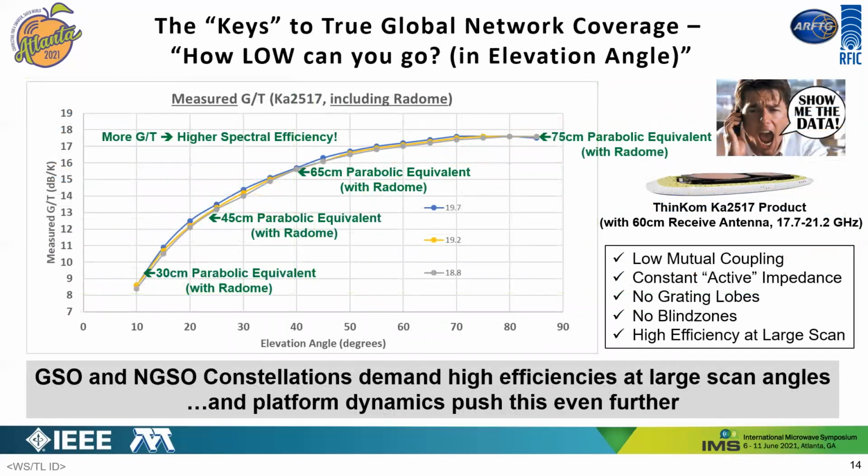In addition to ohmic losses and noise figures, phased array antennas must, by design, scan the beams, and this can introduce another loss associated with undesired mutual coupling phenomenology, wherein the energy radiated by one radiating element is undesirably absorbed by adjacent elements, particularly at higher scan angles. This is termed active impedance phenomenology and is additive to the geometric-based cosine loss associated with the reduced projected area of the antenna aperture as a function of scan angle. These two impacts, the former being design dependent, whereas the latter being physics dependent, combine to reduce the overall gain, that is the G/T and EIRP of the SATCOM phased array as a function of scan angle.